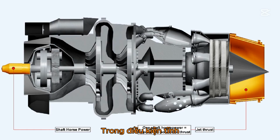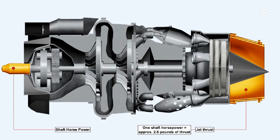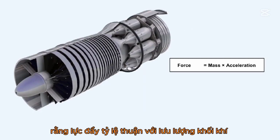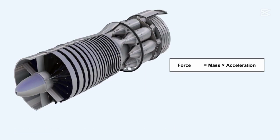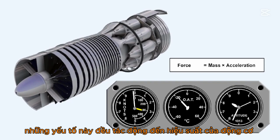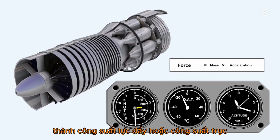Under static conditions, one shaft horsepower equals approximately 2.6 pounds of thrust. We saw from the earlier equation that thrust was proportional to the mass flow rate of air through the engine, and the acceleration we could impart on that air mass flow. Both the mass flow and the acceleration will be affected by changes in altitude, temperature, and airspeed, which all have a bearing on the efficiency of the engine, and therefore the gas energy available for conversion into either thrust horsepower or shaft horsepower.